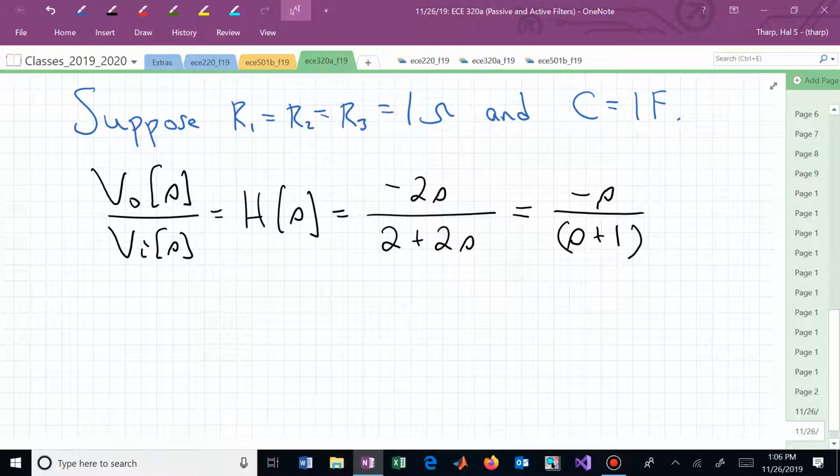You have a 0 at the origin, and what's that Bode plot term produce? Yeah, we just have to walk over to the wall and pin it on the wall, right? It's coming from 0 in an absolute sense, so it's coming from way down in a logarithmic setting or in a dB scale and going up at what rate? What's the slope on that 0 at the origin? There's just one, and that now gives us the 20 dB per decade.